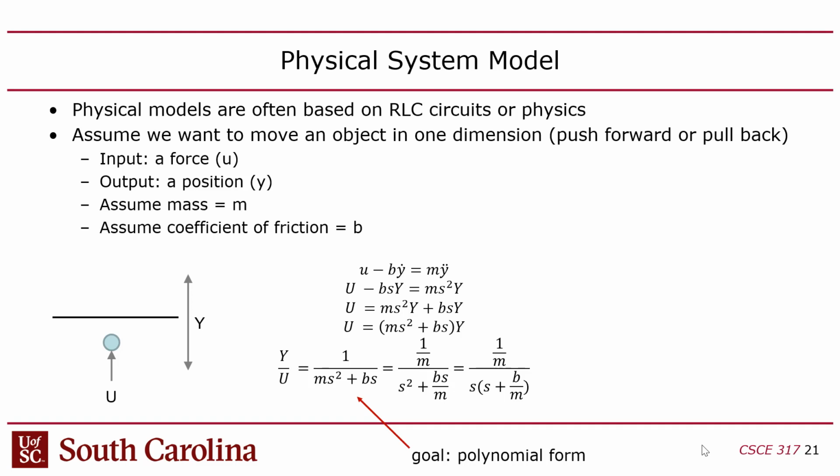Now, in this case, I'm trying to use some shorthand just to show you how these are generally written. Obviously, this first equation is time domain, but you don't have (t) in there. They just take it out. And instead of showing derivatives like dy over dt, they just put the dot. That's what the dot notation is. So this is just a simplified shorthand differential equation. And then if you convert it to S domain, you basically just take the y and make it capital. You get rid of the dots and you replace those dots with s and s squared, right? Because remember, the first derivative is s and the second derivative is s squared.